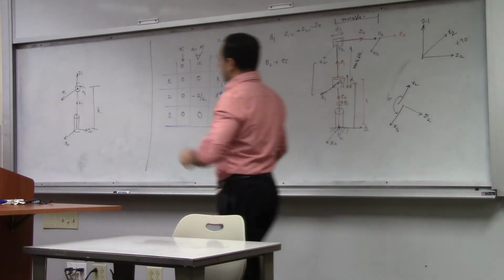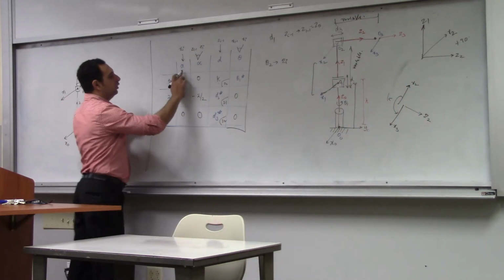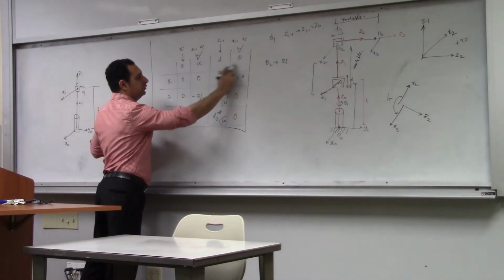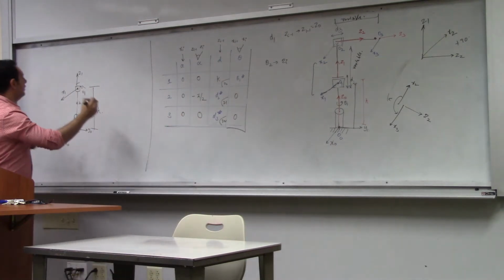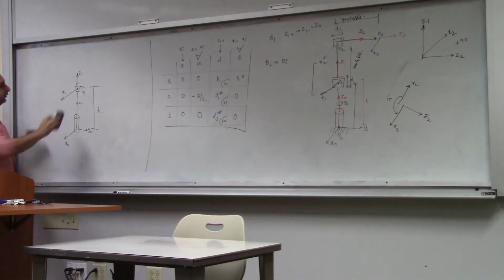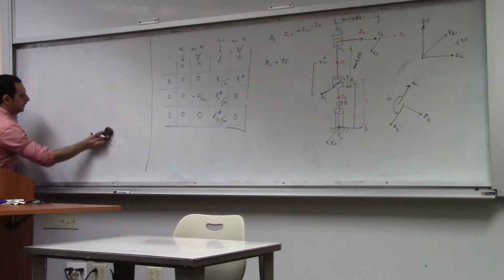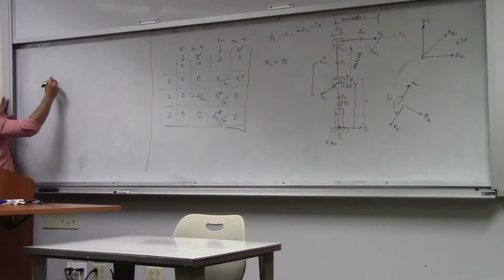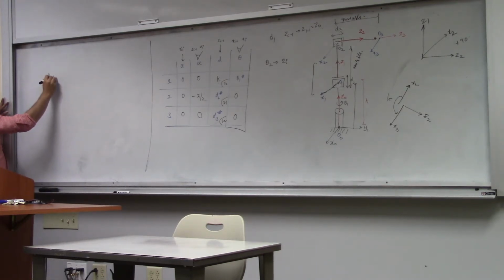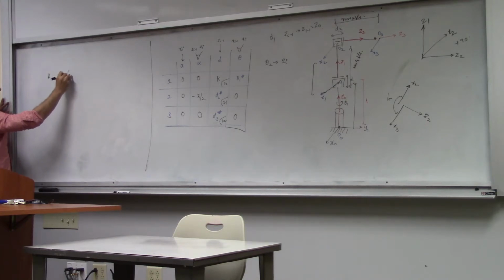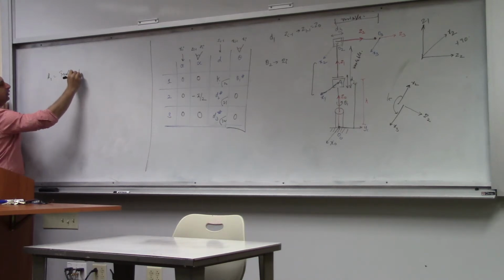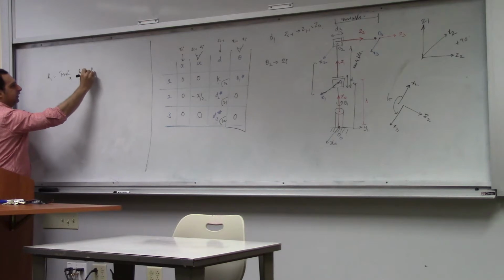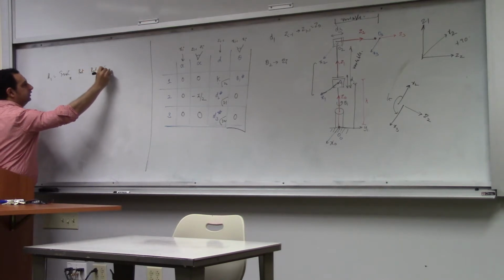Now, when you look at this, you have two displacements and two rotations, right? So when I construct a homogeneous transform with this, I'll set it up as a set of transformations. I'll write translate along x, rotate, and then another rotation and another translation.